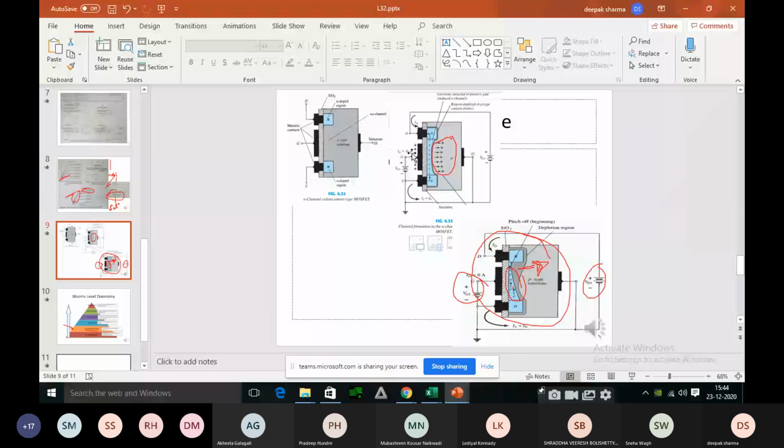better, right? So this is again taken from another textbook, right? So here you are able to see the depletion region. The gray shaded region is depletion region. The blue shaded region, it is the channel. Channel is going on decreasing here. Why? Because more and more positive potential is applied at the drain, correct? Because of reverse bias. So here I'll stop for today's class.